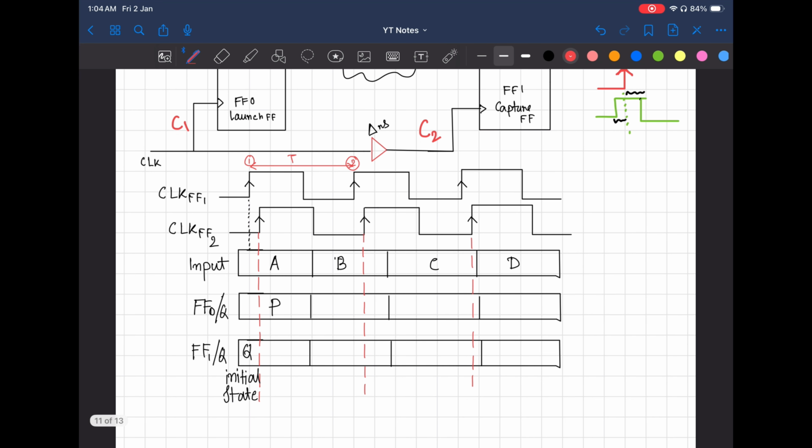with the input sequence and the clock waveform. What it means is that at the same clock edge, P is sampled. Maybe at the next clock edge A is sampled, but what will happen? A can also be sampled at the same clock edge.